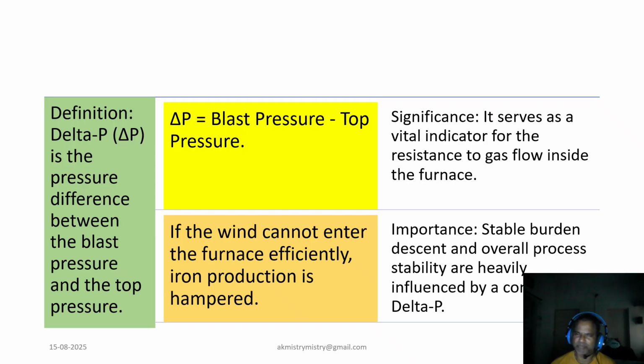There will be a lot of process upsets, and these signify inefficient operation. Consequently, this will be reflected in terms of higher coke rate, asymmetric conditions, and abnormal circumstances like slips, channeling, bleeder lift, and so many things.